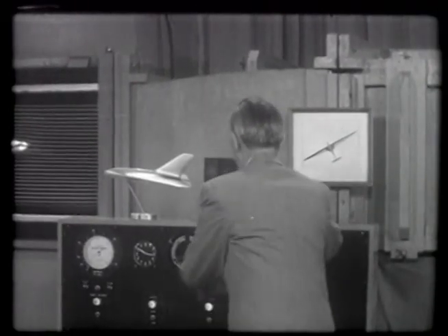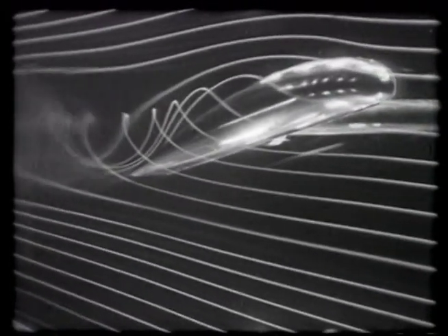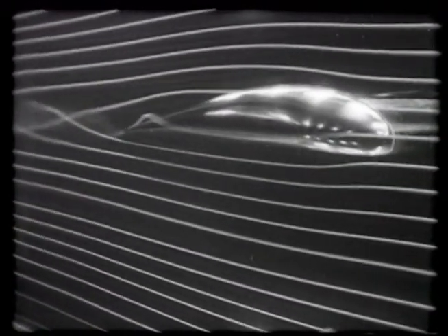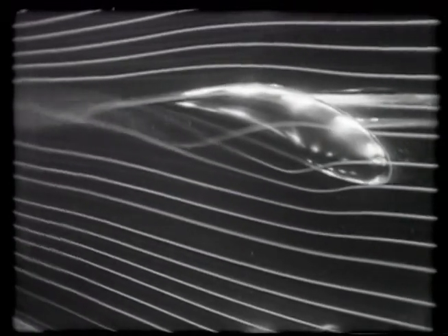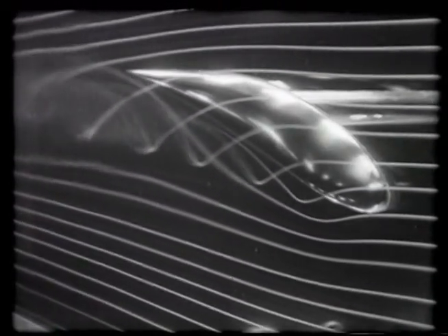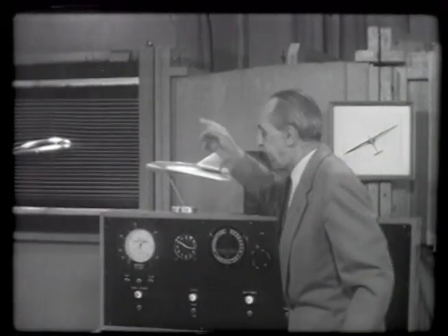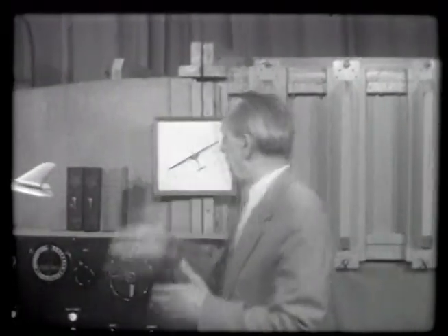Now, when we put this in a negative angle position, you see, go through the zero lift and go to the other side, then you see that the vortex starts the other way, because now we have pressure above and suction below. You might think that what we see here in this pretty small, more or less two-dimensional tunnel is only a kind of a visualization, but it might not be completely true.